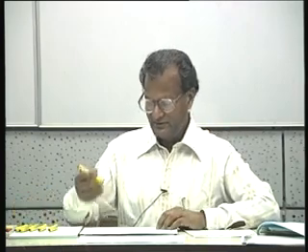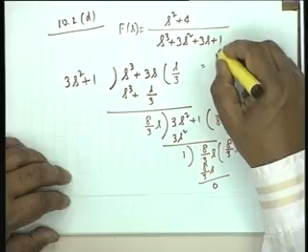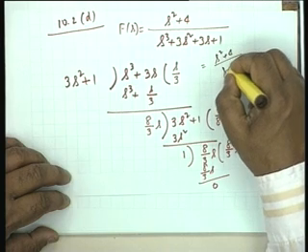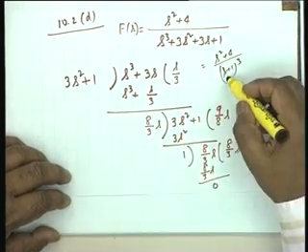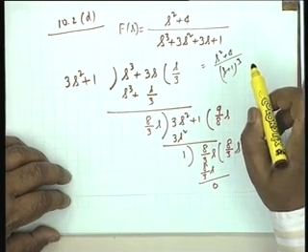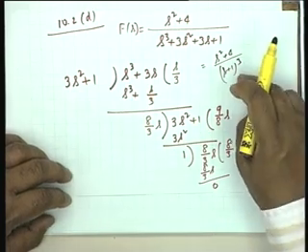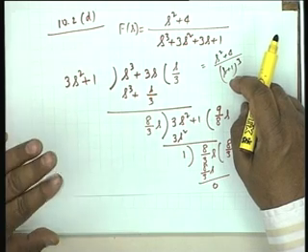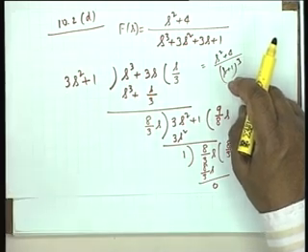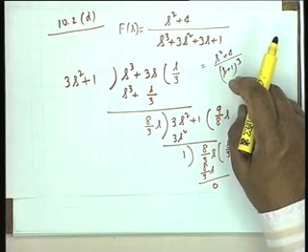You see, what someone is saying is, why couldn't you see that this is s squared plus 4 divided by s plus 1 whole cubed? Indeed it is, which means that there is a pole at minus 1 of multiplicity 3. Now does this violate positive realness? No, not necessarily. Multiple poles on the j omega axis are not allowed.